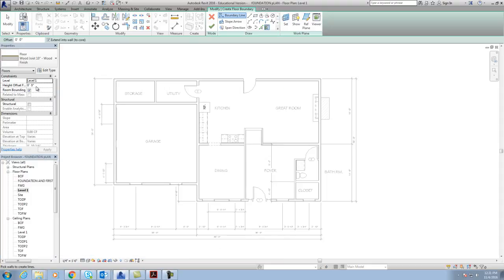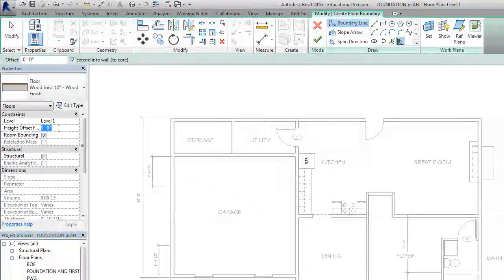And I want to offset this up 0.75 for that flooring, so everything will be offset. I'll show you more about what that means in a minute. 0.75 inches. But you just have to think about that. We put that flooring in, and we had that 3/4 inch, 0.75 inch hardwood on top of it, and it'll try to make that your floor where the wall studs are setting. You don't want your wall studs setting on your hardwood floor. So that's the reason we do that. That'll lift it up, and that'll put the wall studs exactly on our flooring.